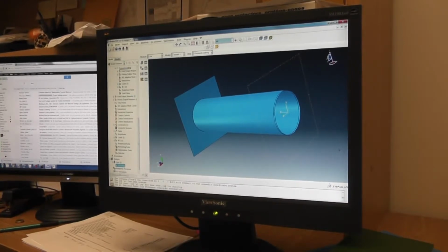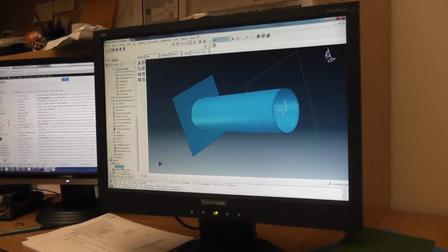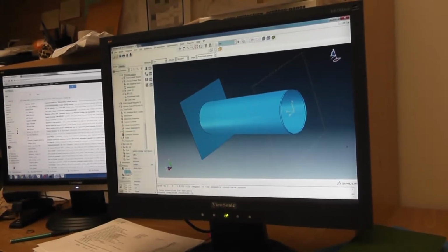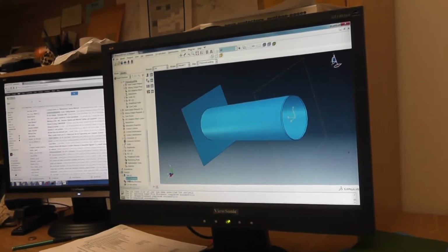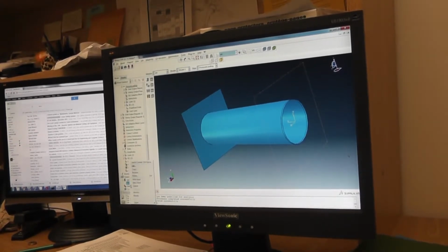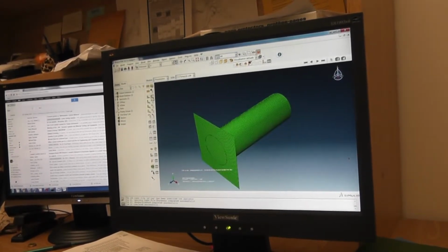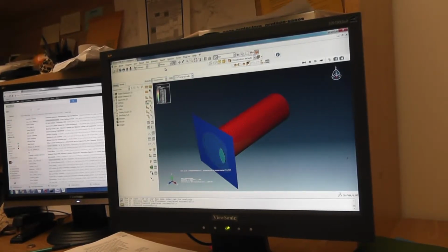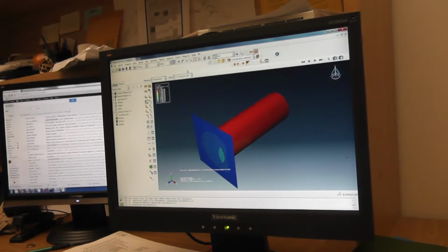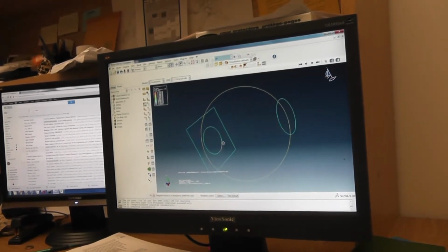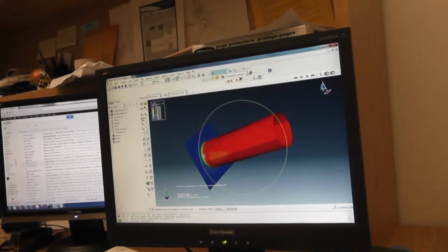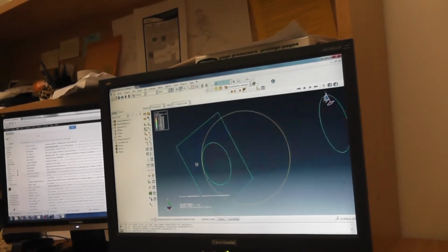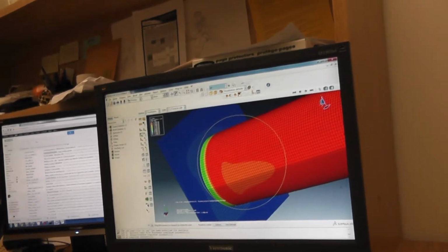Input file processor completed successfully. There was no issue with the model. And now it has completed successfully. Let's look at the results. Well, it's deformed. Let's look at the stresses, the von Mises stress. You can find the maximum von Mises stresses here, as expected around the weld. That's why in this area we have to make sure that this doesn't fail. But the maximum von Mises stress is still very low.